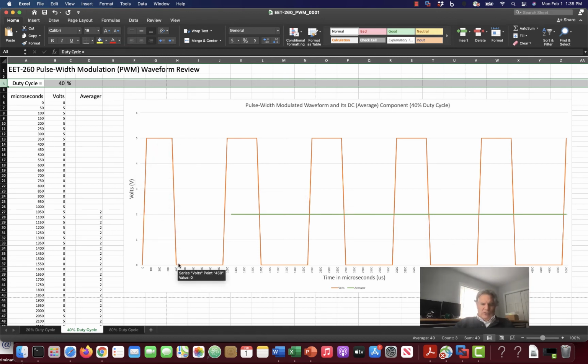The system can only go between 0 and 5 volts, but we get to play with time, and that's where we trade kind of something approaching analog time. Obviously we can't get complete continuous time. There's some number of samples. We count something here to time this, but we can get a pretty smooth, almost seemingly continuous range of voltages here by just playing with the time that we drive this high.